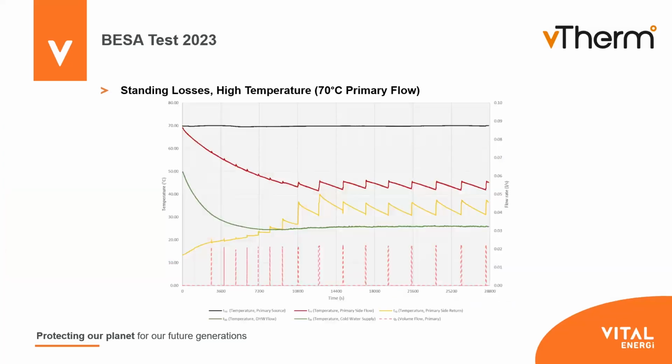If you remember, I spoke about the domestic hot water keep warm cycle, and as you can see, it will start at, let's say, the temperature within the HIU plate has dropped down to 42 degrees, 44 degrees, and then it'll get a blip, maybe 10% open of the valve. That will then heat it to the 50 degrees, and then it'll gradually degrade again over time.